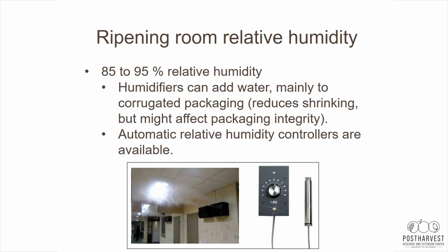High levels of relative humidity, especially in a cold room, can cause condensation, and then the corrugated boxes might be affected. There are other issues of disease and so on. So relative humidity management and handling is very, very important. And as I've said, it's somewhat trivial to handle temperature, but relative humidity is still evolving, even to this day.